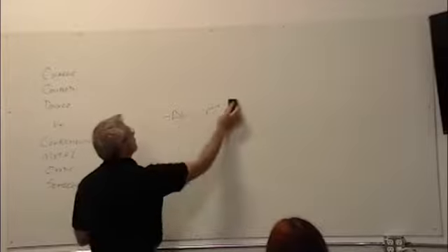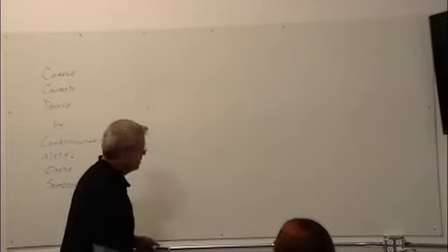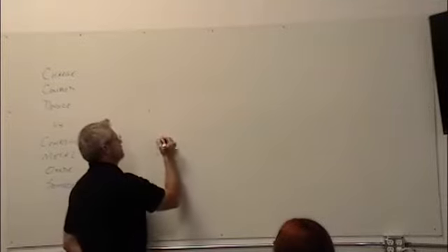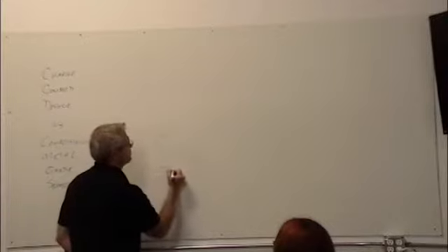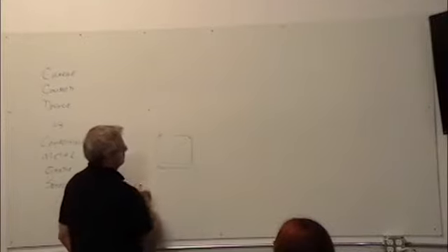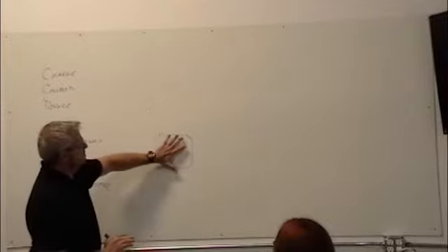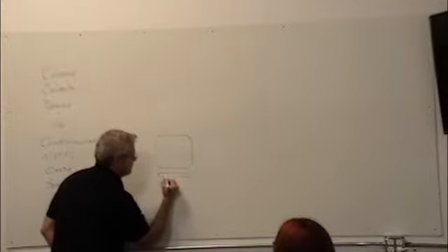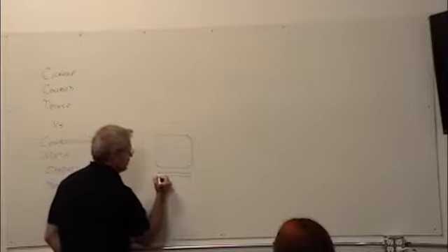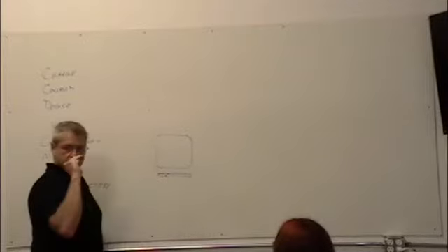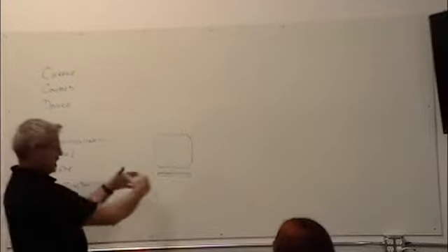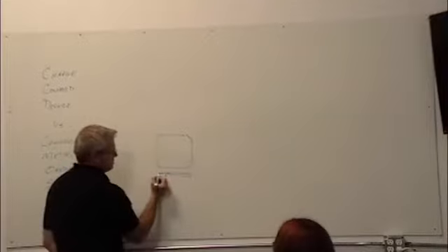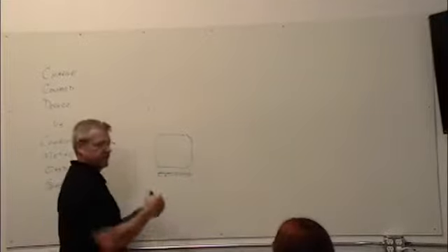So we'll start off with a solar cell. If I've got this little thing like this, it's not going to do a lot of energy, but your standard solar cell on your roof is made up of pieces that are not quite that big. If you lay this on its edge, this is a piece of P-type silicon, usually. It has an N-type deposition on it. So it's a giant freaking diode. It's this big around. And energy that comes in and lands in the diffusion region here gets swept both ways.